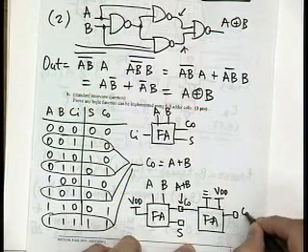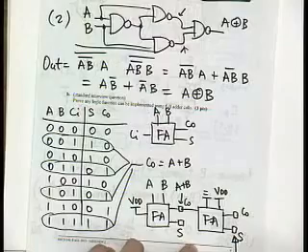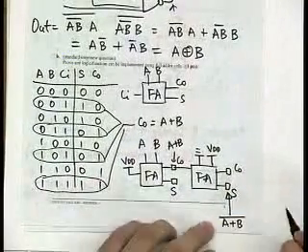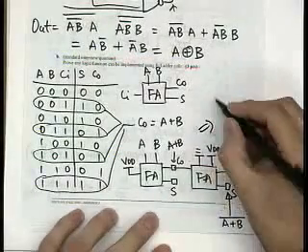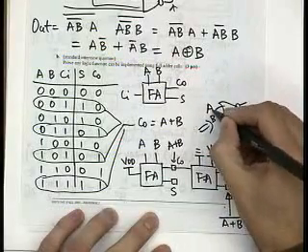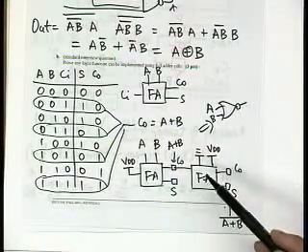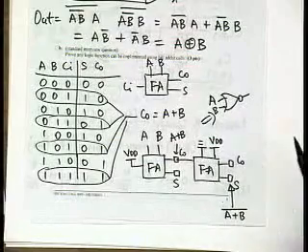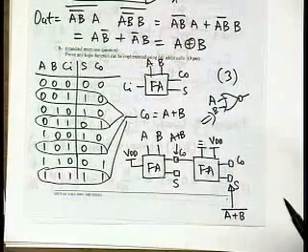So I have carry out here, and I have sum, and this is now equal to A NOR B. So this now basically implements this function. You can do a similar exercise to figure out how to do this with NAND, and that's what we provided in the exam solutions. And that's basically also another 3 points or nothing if you did this.